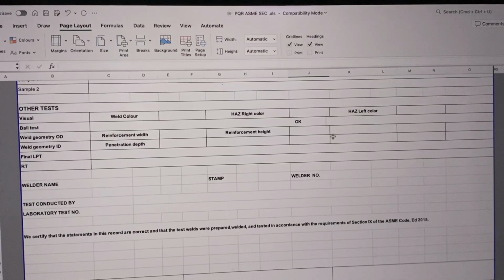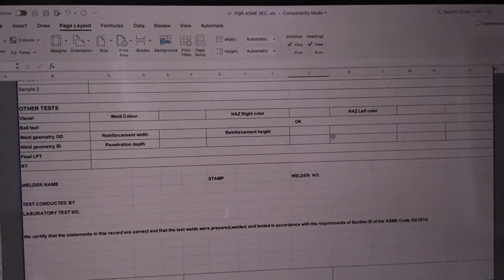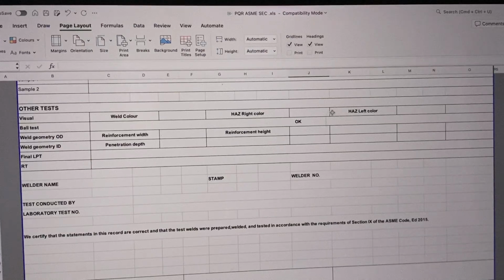So the length of the pipe before setup, after setup, and after welding, and the diameter of the pipe before setup, after setup, and after welding are required to be recorded and registered into our data log, and then transferred into a digitized system. You can scan and upload images of the data you have logged, or key it in on a Word or Excel sheet, or you may have software in which you can do it.